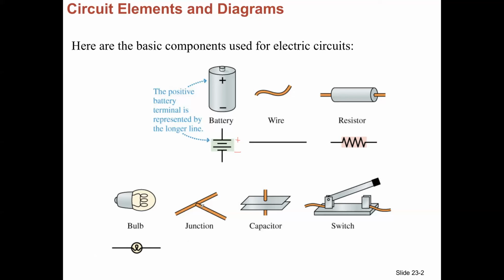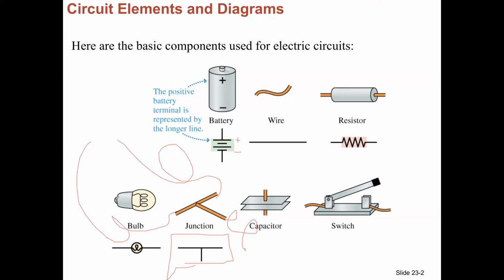A junction of wires, where two wires meet, is more or less basically like you would expect. The only thing here is that regardless of how they meet, if they meet at a right angle or not, it's always drawn at a right angle if possible. So you try to draw the junction in a way that simplifies what's going on. There might be loop-de-loops here or something where this wire is going off this way and this way.